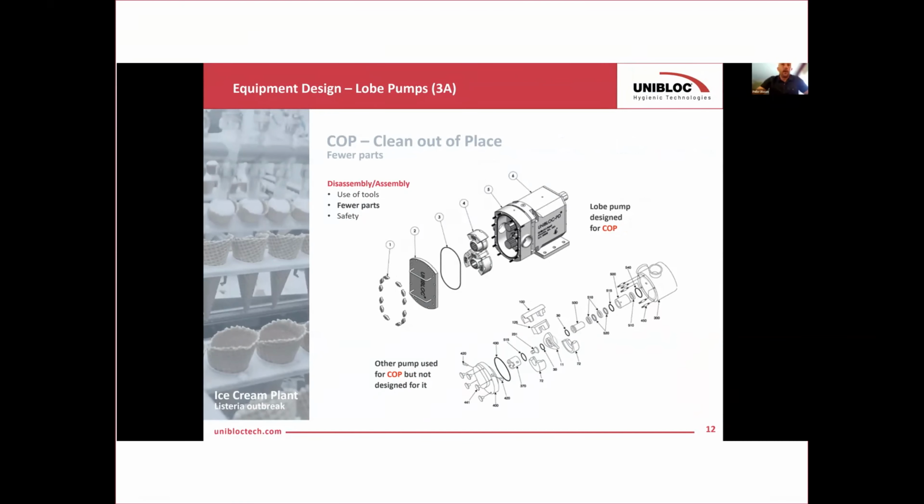The top picture there is a pump that is designed for COP, and the lower image is a different type of pump that is used for COP, but it's not really designed for that purpose, because if you have to take the equipment apart, you want to make sure you have few components to make it easy. And the pump below there is very complicated compared to the pump on top.